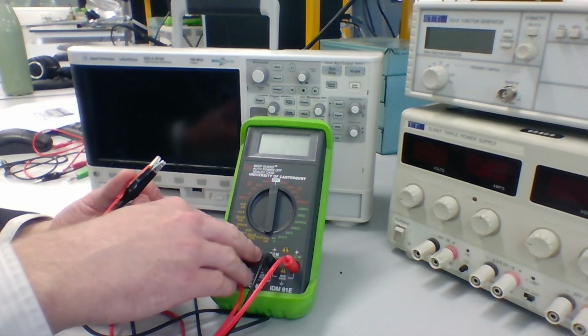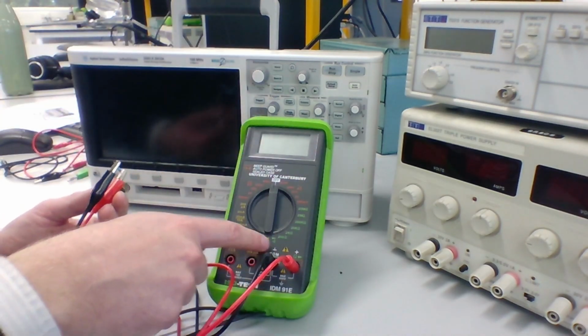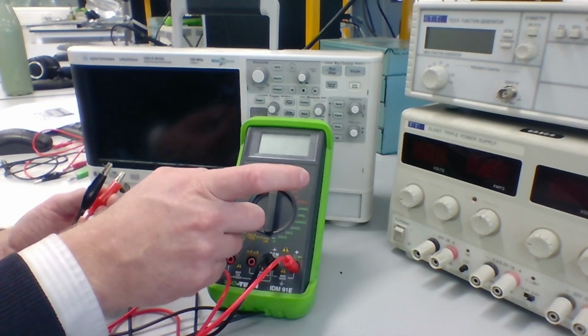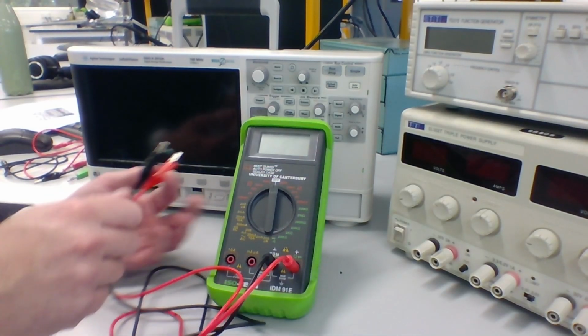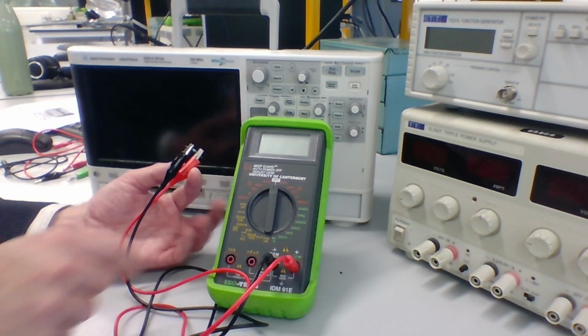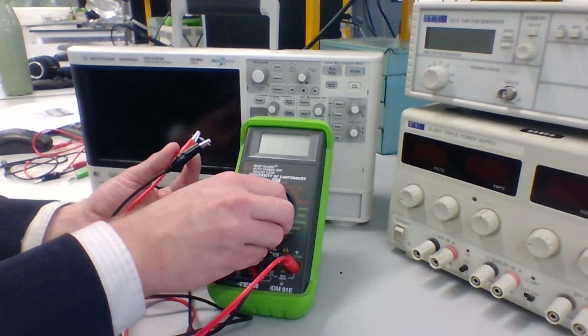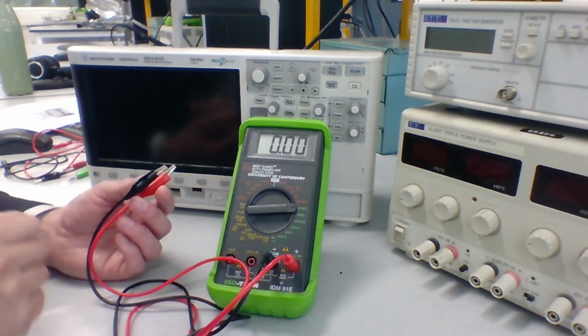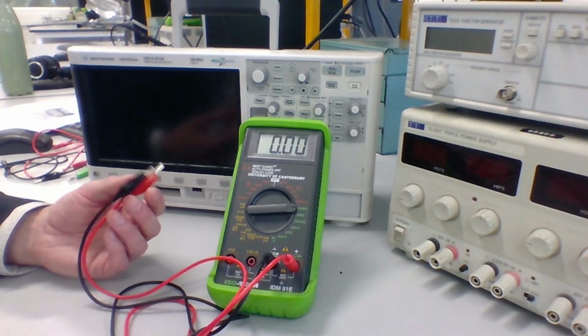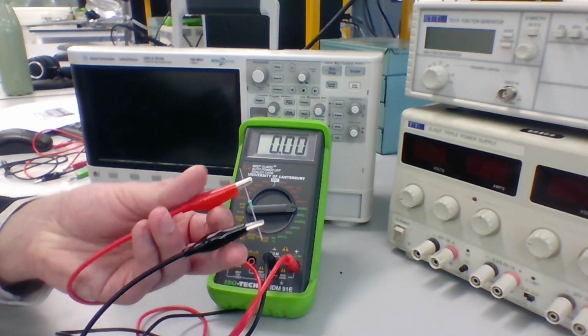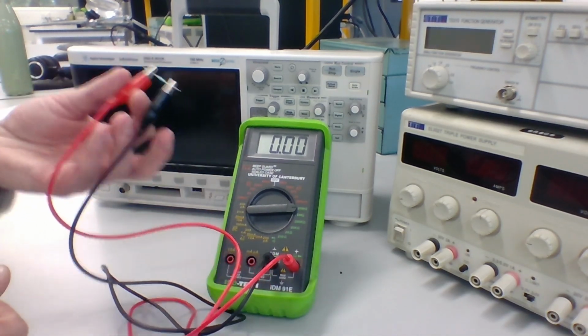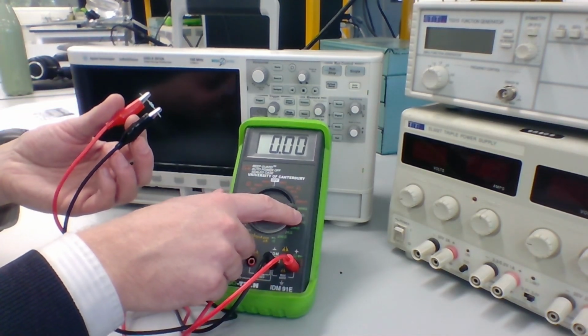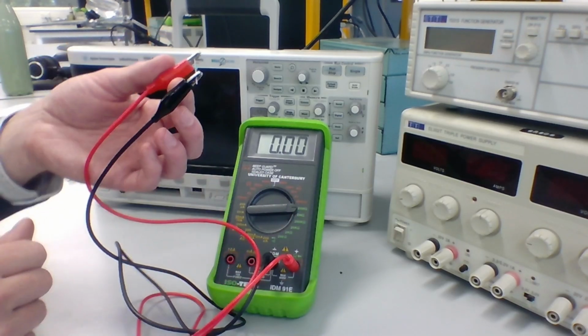Some will auto-range throughout the entire possible range. Others will auto-range within a set range, which is what this multimeter does. So we have to figure out which of these ranges is appropriate for this resistance. So if I turn this to the 20 mega ohm range, you see we get 0 on the multimeter, which indicates that either this is 0 resistance, or more likely, the resistance is far smaller than the tens to hundreds of mega ohms range, and so we can't measure it.